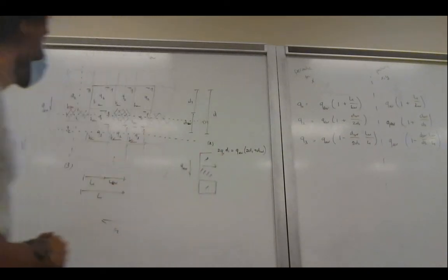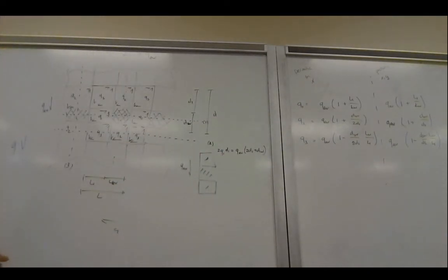So what we can see is that the effects of our cutouts, depending if we have a cutout only in X, or periodicity only in the longitudinal direction in X, or we have periodicity in both longitudinal and circumferential direction, so both in X and Y, will have its effects on our shear flows in the panels around the cutout. So Q1, Q2, and Q3. And of course, that effect needs to be quantified.